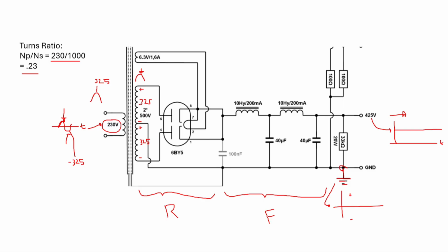Ooh, I did that so wrong. You know what? I'm not even going to cut this. Here's what I should have done. This is extemporaneous speaking for you. 500 volts divided by 0.707. It's 707 volts right here. 707 volts peak.